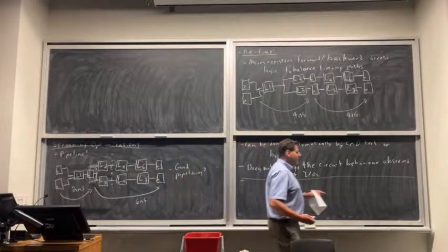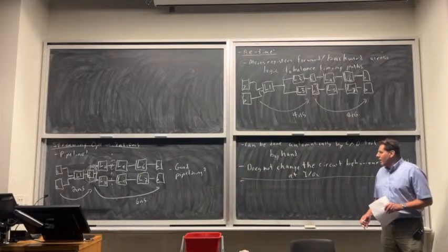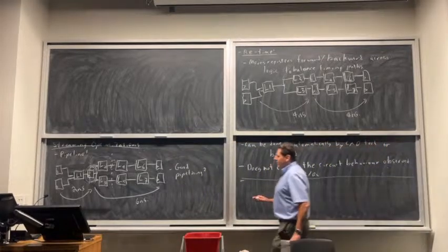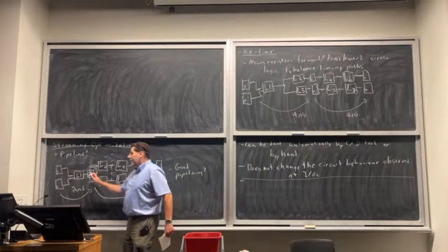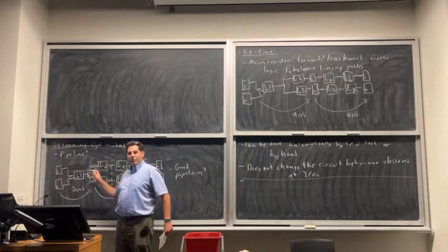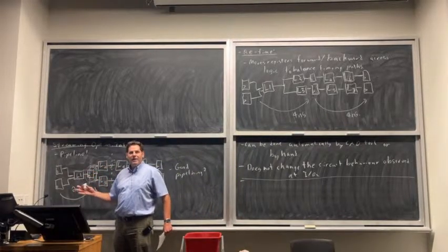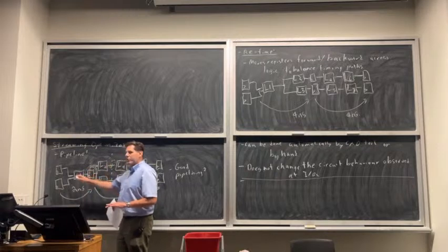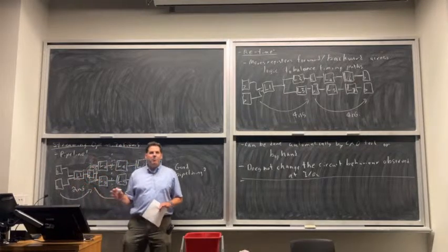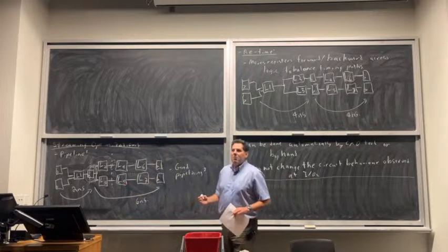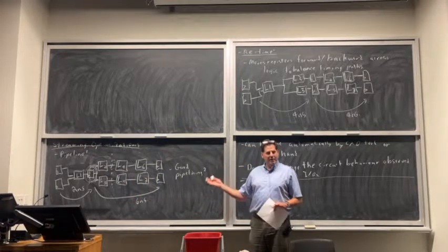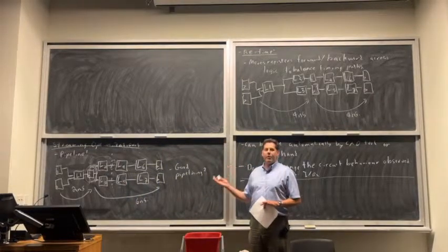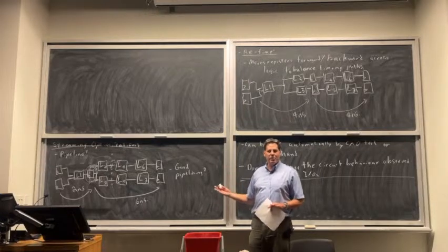The reason that's useful is these CAD algorithms use delay estimates and they run at multiple stages in the CAD flow, certainly in Quartus. Early on, before they've done much of the design implementation, during synthesis, where you're just deciding what the logic is based on the Verilog you wrote, they can move the registers quite a bit, but they have pretty poor delay estimates. So delay estimates can be wrong.